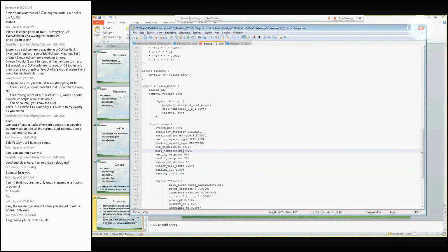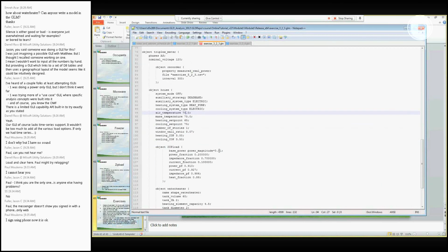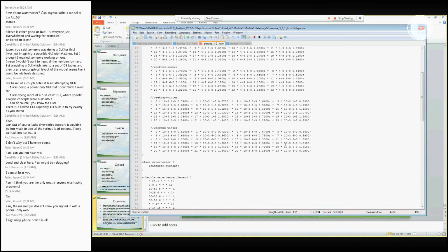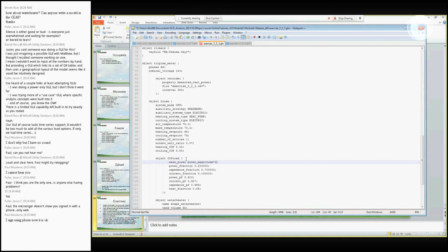So we're basically just initializing this close to the cooling set point so that we start in steady state. So now we just have basically an average run-of-the-mill house. We're recording the power at the meter. We have this zip load that will do something on the order of about 1.5 kilowatts of other loads on peak. If you look at the schedule up here, at the lowest, it's going to be something on the order of about 630 watts being consumed by every other load. Every other load in this case being not the HVAC and not the hot water heater.